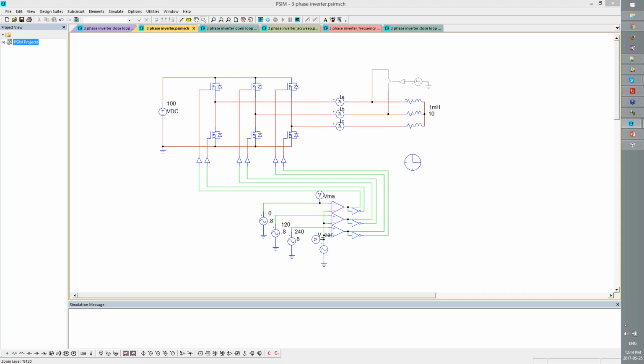So yep. This accepts any TI control card, and so this slots in, and then all of the analog and digital input and output pins are mapped to this header, and so there are test points. So we'll probe some test points here as well, so that you can see some of the signals that are coming in and out between the HIL unit and the processor. I've got a little USB oscilloscope here called a PicoScope with some test probes, so we'll be able to probe signals. This is the HIL unit itself.